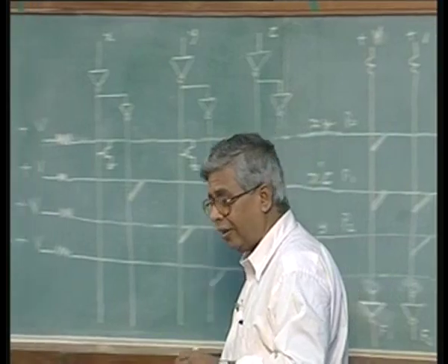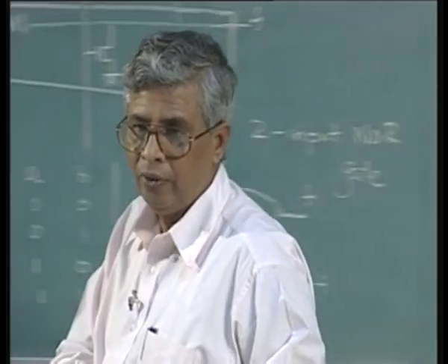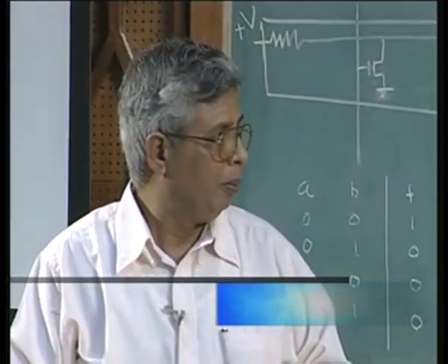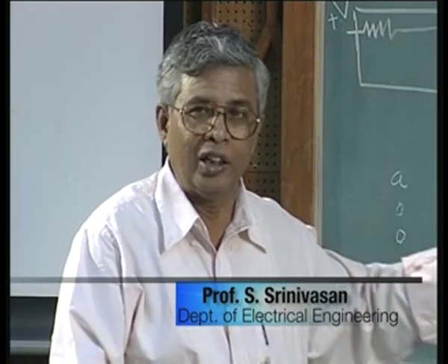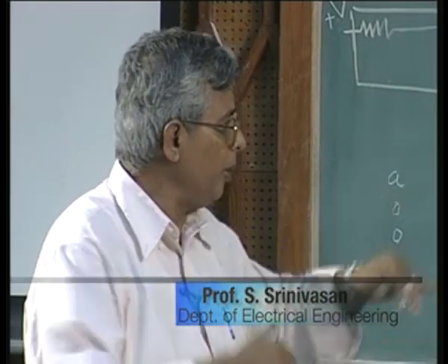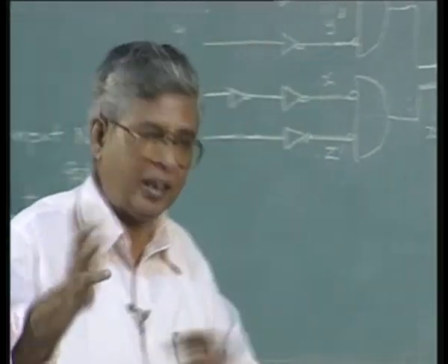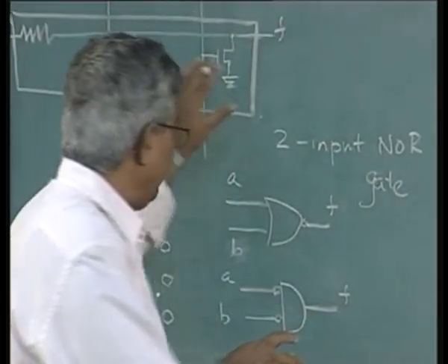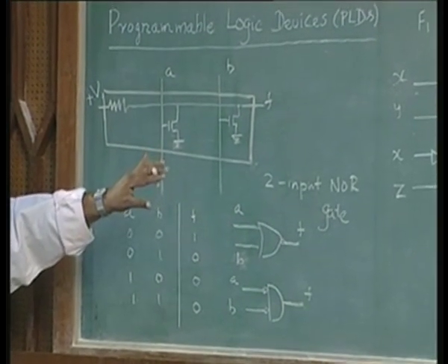This is not hardware. As I said, I am not going to talk too much about the implementation technology aspects of programmable logic devices, but this is a circuit technique we are using, because I am given a function of AND OR inverter and I am asked to implement it using NOR gates. I need to have this type of circuit technique. So the circuit technique of converting the AND OR inverter into a NOR logic family is what I wanted to explain to you using this technique.